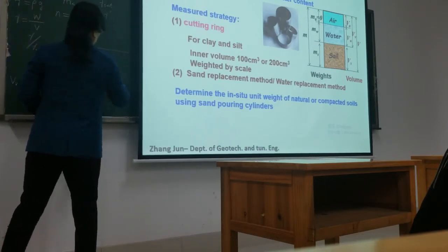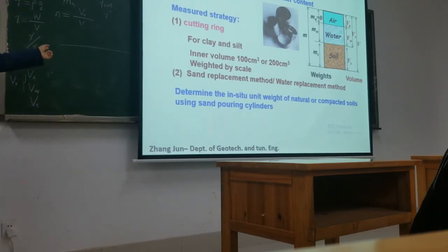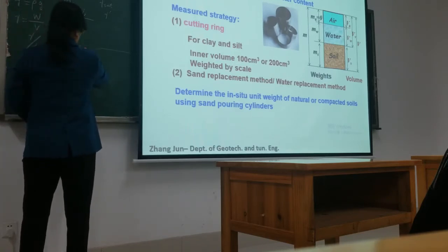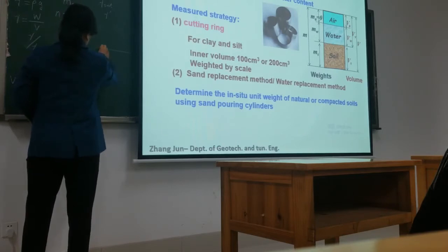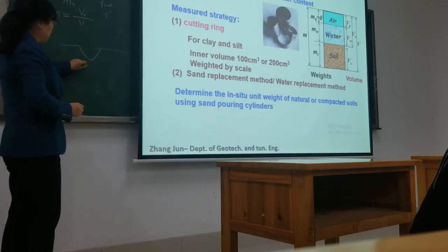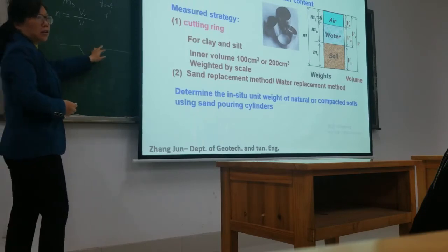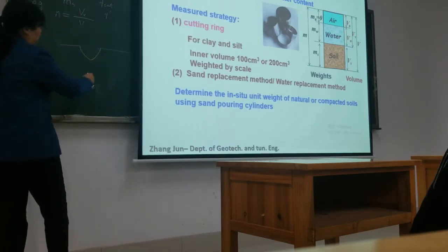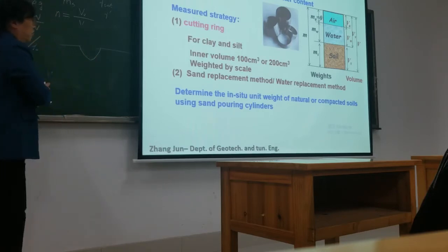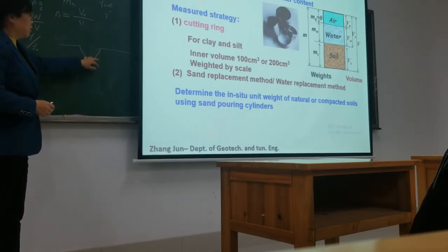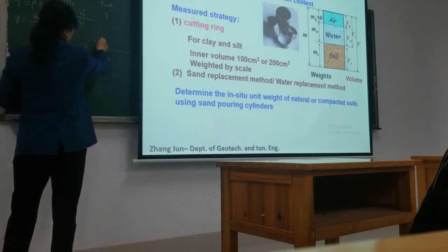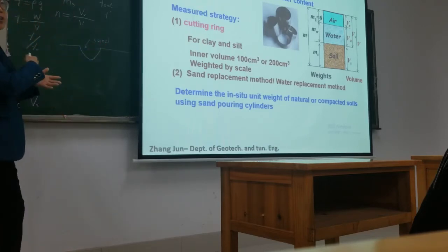Here's the ground in situ, and we dig a pit like this, and we measure the weight of the soil, okay, and fill it with sand.